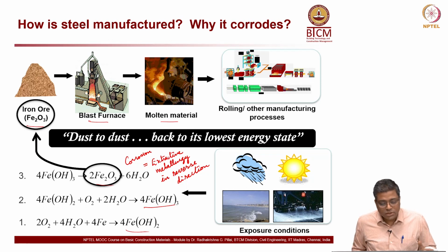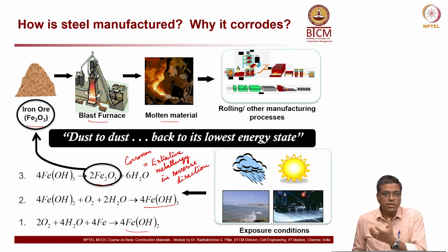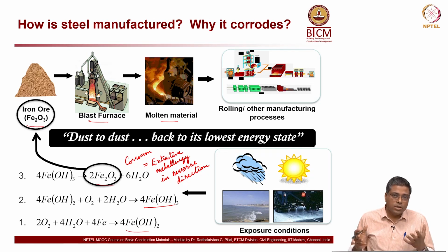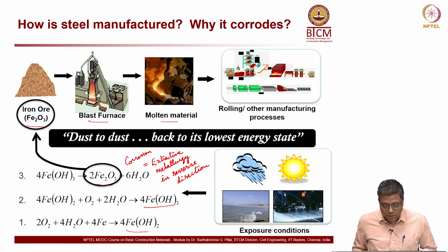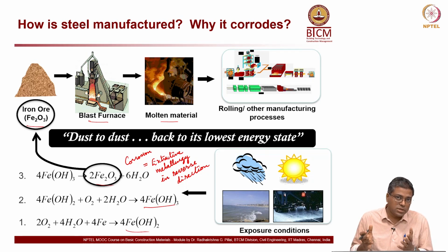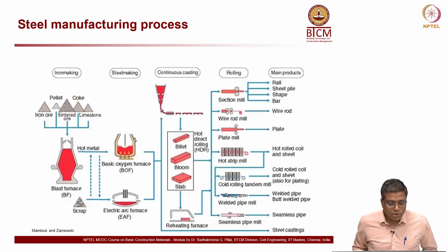Okay, so essentially during the manufacturing process of steel, the energy level of steel increases because of the heat treatment and the mechanical treatment which is given, and because of that high energy level, when it comes in contact with the environment, it will try to go back. Now, this rate of corrosion you can control by various means. Okay. That is all advanced level courses. We will not cover those things in this class, but what you need to know is that when you talk about stainless steel, this rate of corrosion is very, very small as compared to the other typical steels which are used.